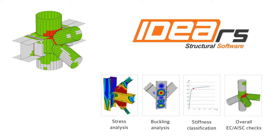In this video we would like to show you not only how we design a connection with IDEA StatiCa, but the workflow that we can follow if we want to combine our main structural analysis software that is used for the global analysis of the structure. Of course, a steel connection can be very easily created within IDEA StatiCa, but still it is very useful to import the connection from the main structural analysis software because we can also import automatically all the forces that are applied to the node. That allows us to save time, of course, and avoid any typo mistakes when the input of loads is done manually.